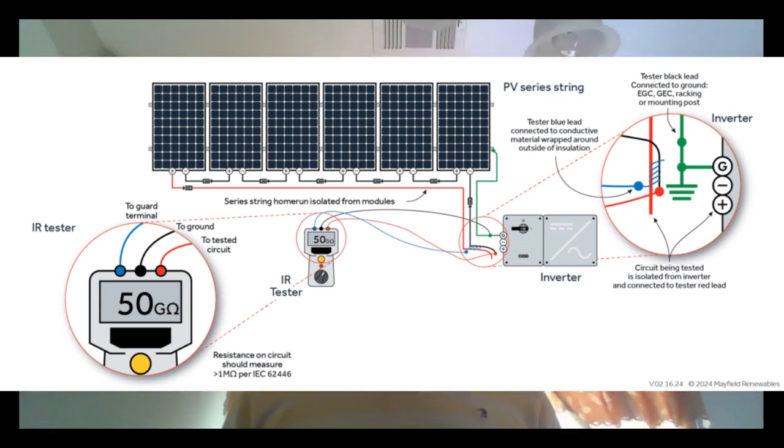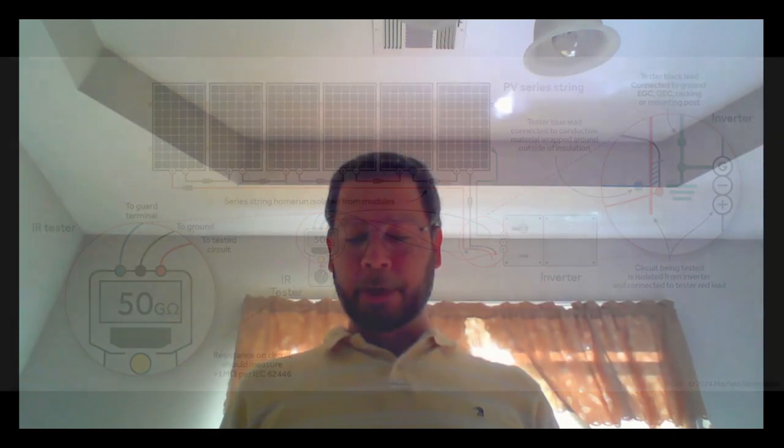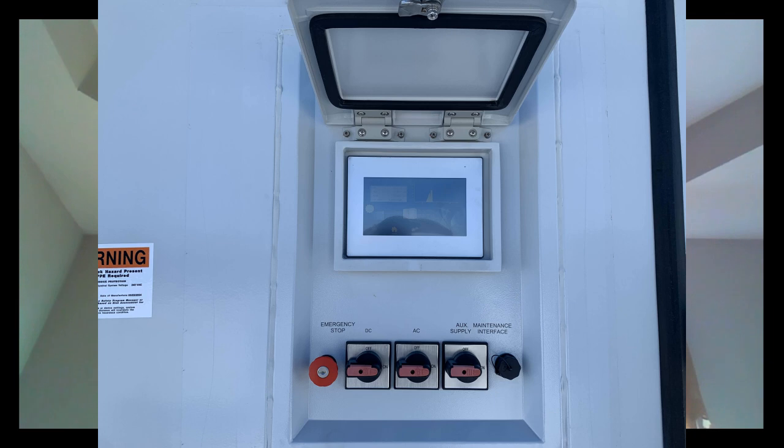Intermittent ground faults may also result from moving parts, such as tracking solar arrays. The fault may only appear at specific times of the day. In that case, reset the inverter and use the monitoring system to identify the time when the GFDI tripped. Do your troubleshooting around this time to identify the fault location.